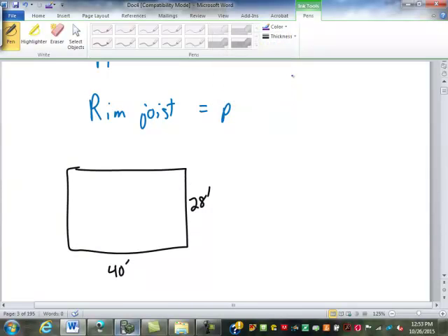When would you not need rim joist around the whole foundation? What's that? You still want to put rim joist around it for the floor. You're going to have something around the whole foundation. I'm talking about if you have to special order the rim joist, like if you have I-joists. If you're going to run I-joists across here, you have to have a special rim joist, because an I-joist, a TGI or whatever you want to call them, is not designed to handle what they call a compressive load.